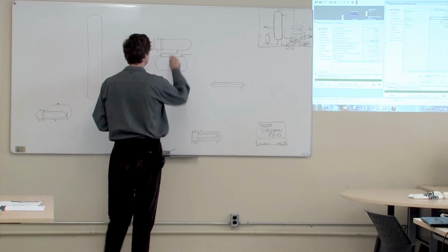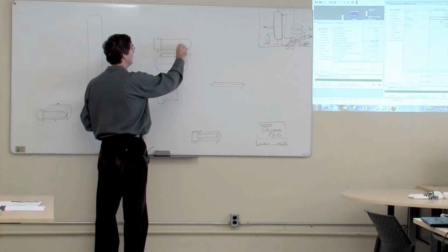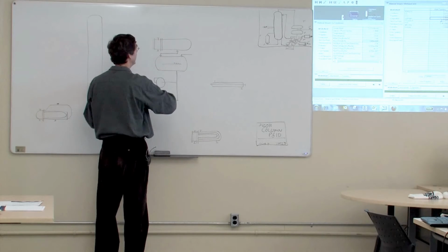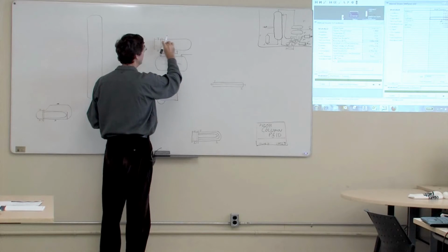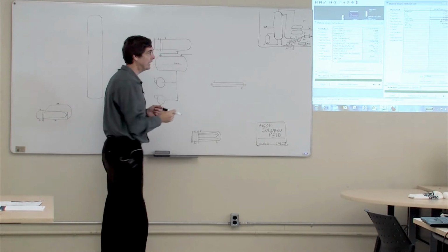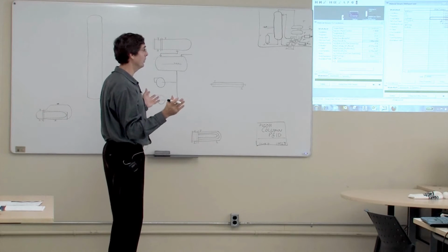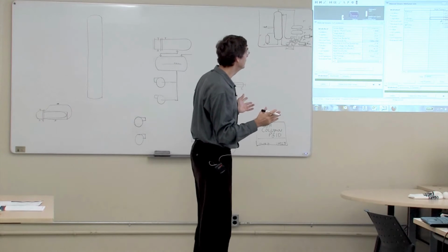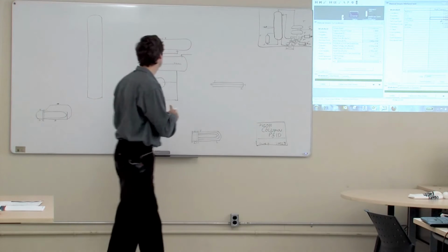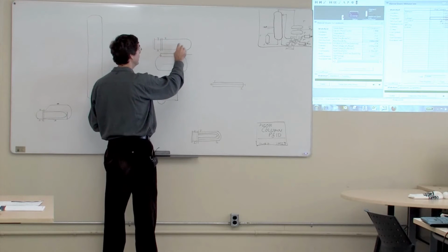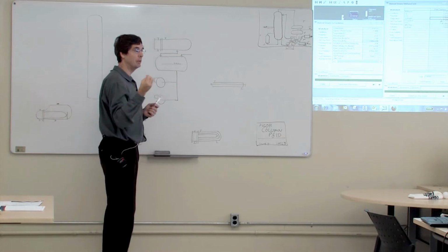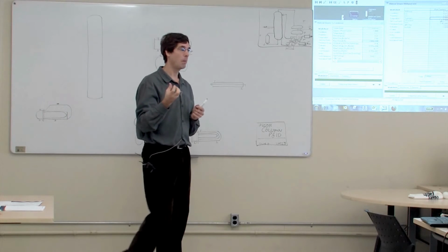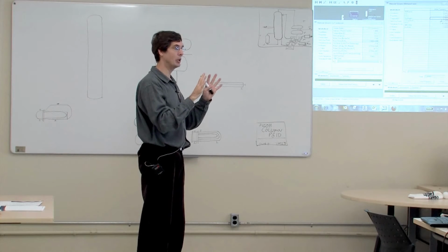And I might be a little bit worried about this because I'm going to be coming into the condenser with very high velocity gas. It's going to be condensing through the condenser, and because we condense nearly, I don't know what it is, 99.9% of it, you do the math, I guess. But a very high percentage of it. So down at this end of the heat exchanger, the velocities are going to be exceptionally low. Like the gas is just going to be drifting along.